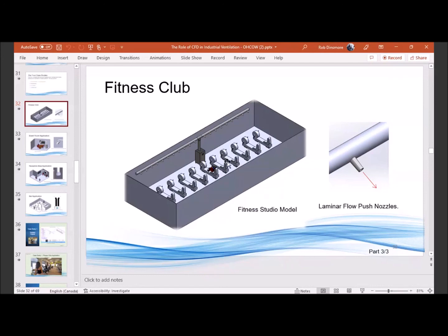Really, what should happen in this entire facility to address that issue is that the HVAC system should be ducted where the inlets are all at the floor level, and we're supplying all our air up in the ceiling space. Not terribly difficult to do, but if we can pick the air up at the floor, HEPA filter it right at the floor, and blow it back into the return of the system, that will go a long way to addressing the challenge that you bring up.